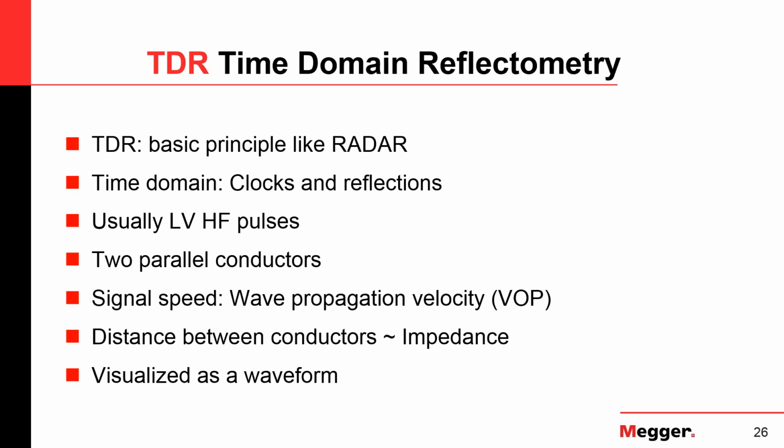So this is what I mentioned before. For different materials, the values can be different. And as I said before, this L and the C in that formula of the cable's impedance are purely defined by the geometry of the cable. This is the same for the inductance and the capacitance of an overhead line, and it's very much true for a cable. So the distance between those two conductors, in terms of our single phase cable, which is the center conductor and the concentric neutral, is proportional to its impedance.